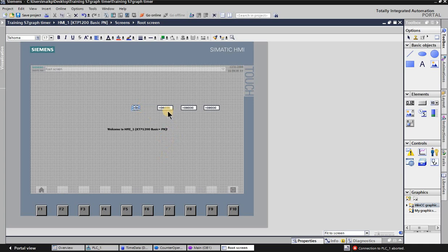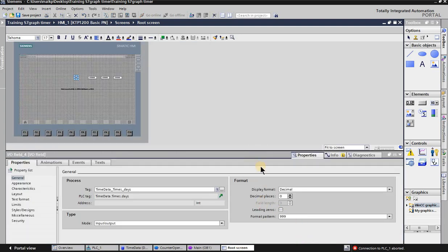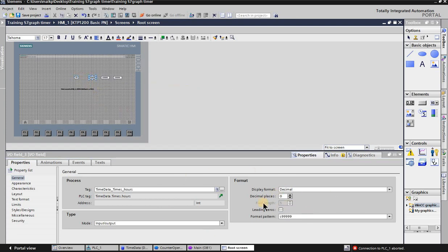the size. So now we go back on properties, and a little trick here: if you have multiple objects that you do want to modify in the same way, you just open up whatever property page you want, and then you can click from object to object, and it will lead you to the very same property page for that other object, so we don't have to click around like crazy.